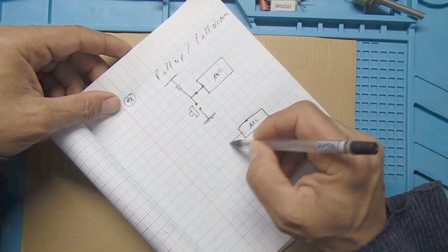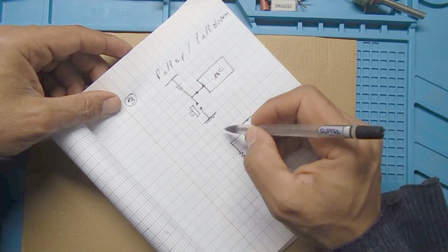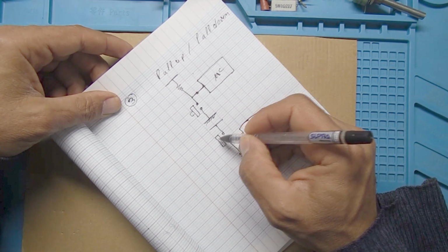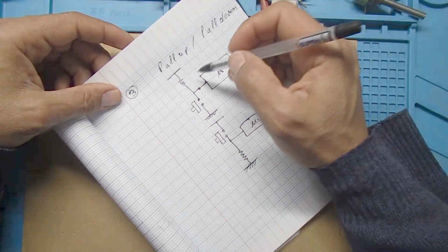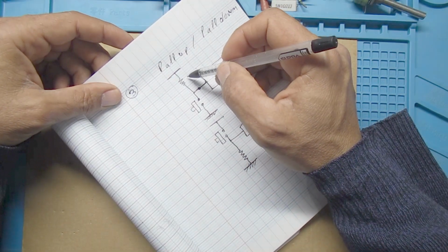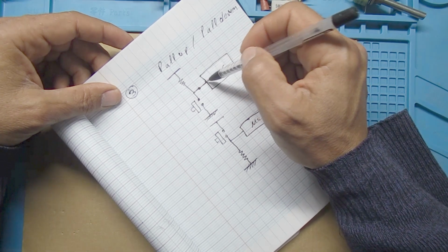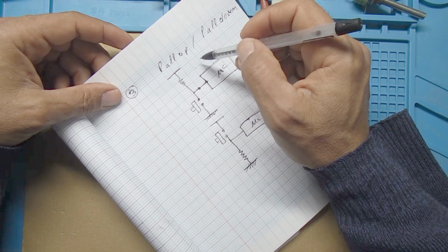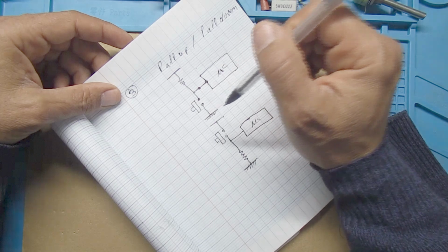Here we have the microcontroller. We can use a resistor to pull down the input and use our push button here. The value might be 4.7 kilo ohm or 1K or 10K. It depends on the input resistor of the microcontroller. If we have a limited power source, we use a high value of this resistor.